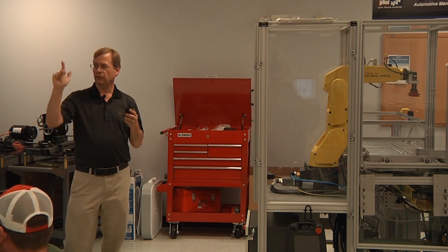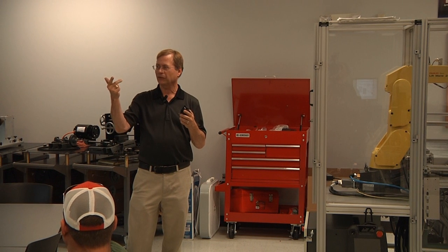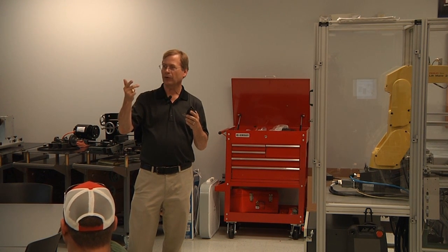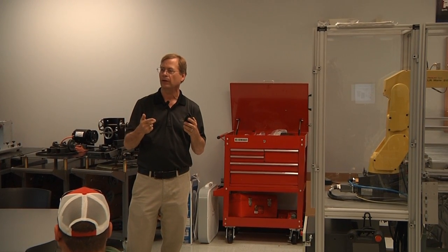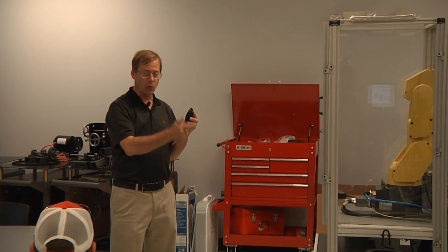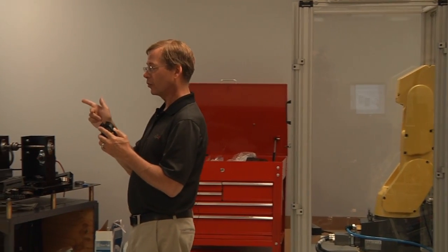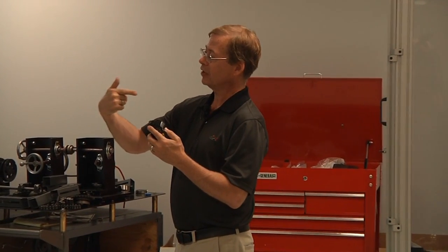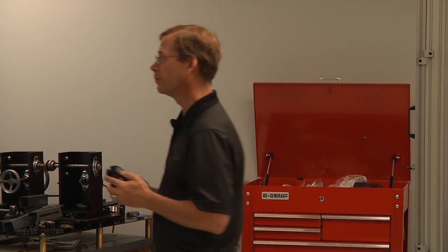So we're going to use this right-hand rule, and it's very easy to use. You carry this wherever you go. So it will help you when you're teaching to remind yourself what is X, Y, and Z. Just remember, it's the robot's origin, not yours. So if I'm facing the robot, don't think that X is that way. The robot's pointing at you. The X positive is coming at you.